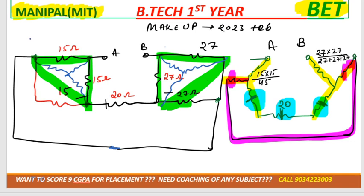We are calculating resistance now, RTH. So for calculation of RTH, the voltage source must be removed. So after solving, A, B as it is, it will become a single resistance, right? Solving blue and purple, these two will become parallel and it will become a single resistor. Now all three resistors are in series. So this would be your RTH.